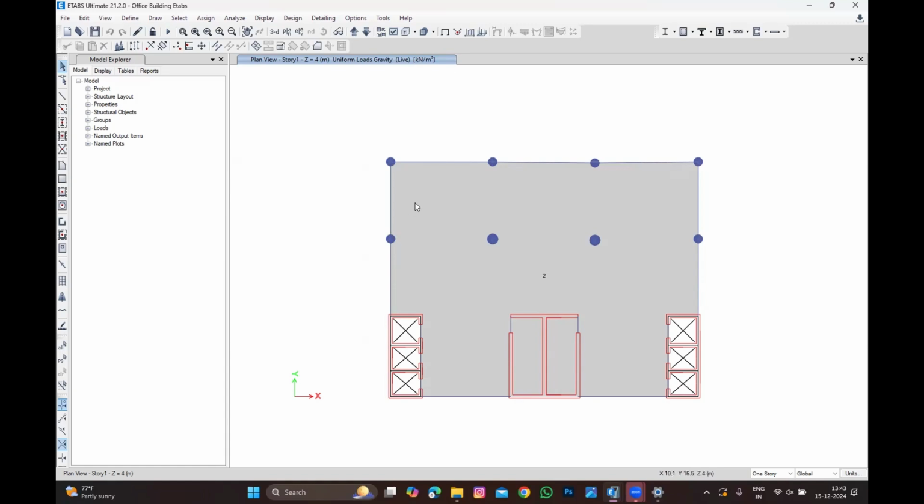कैसा consider करना है देखो भाई. इधर देखो. While you are applying the load on the beams, you need to select the beams, and don't go for precisely selecting the beams. Just randomly select it in the beams. Even the slabs will be selected, doesn't matter, because when you're applying the UDL it will never act as a slab. It will act as a member only. Even if the slab is selected, don't worry. Even the wall is selected, don't worry. सही है ना? But column को select मत करो, है ना?